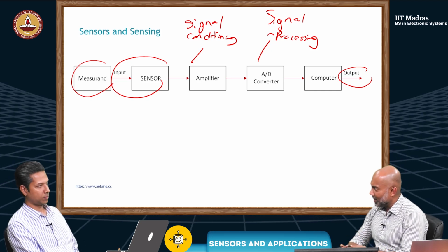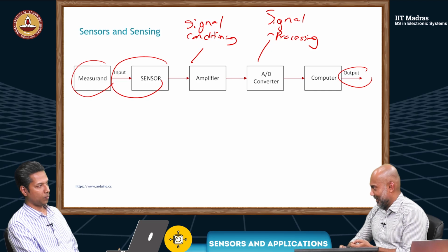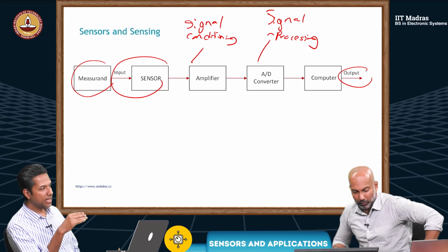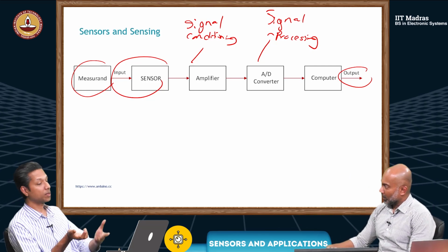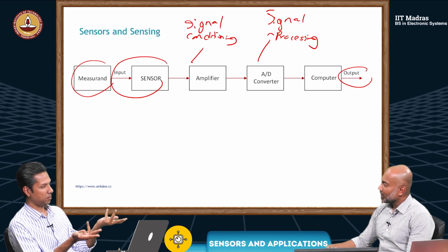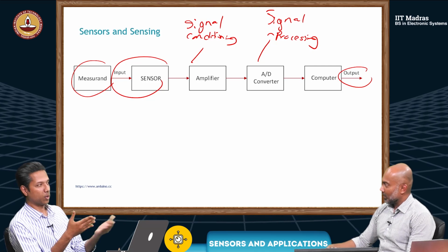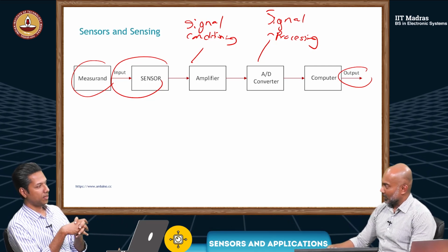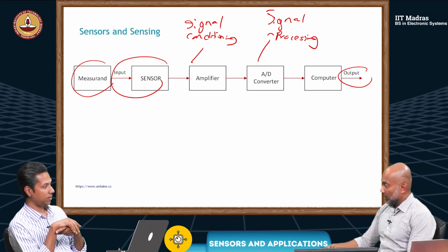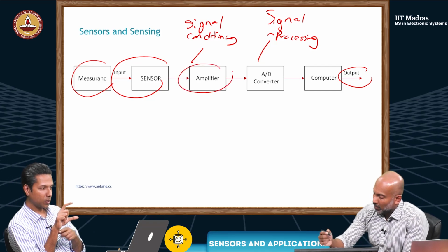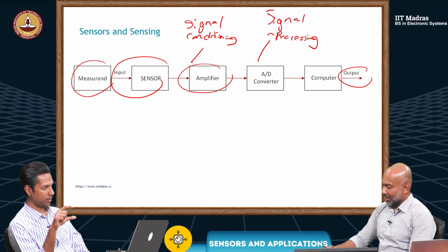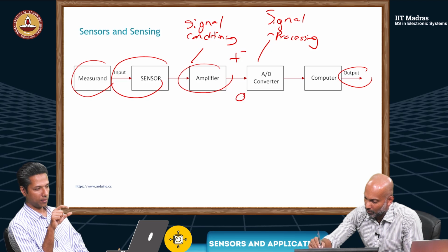So you're now basically playing with the measurement, right? You're amplifying it now. So the output from the sensing element, for example, if it was a thermocouple, it may be some millivolts. Yes. Depending on the temperature, and material selected, etc. And you are going to give it to an analog to digital converter. Correct. And that analog to digital converter also has some input range, I think. Yes. Let's say 0 to 5 volt. Yes, exactly. So this has a 0, let's say plus 5 volts.